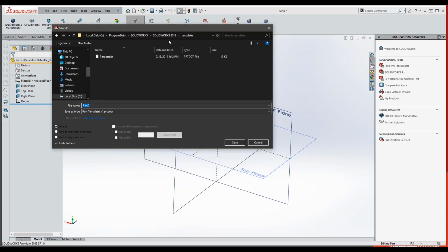And you can see it jumps us right to the sort of pre-programmed SOLIDWORKS location. And I'll show you why here in a minute. They don't have to be here. If you are using PDM, we definitely recommend that your templates go into PDM and are captured under a read-only so that they can't get tampered with.